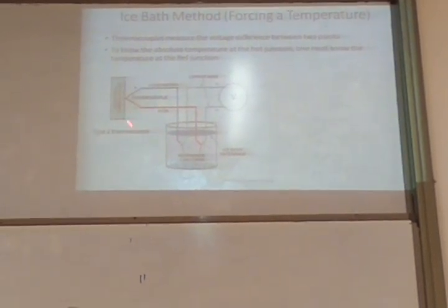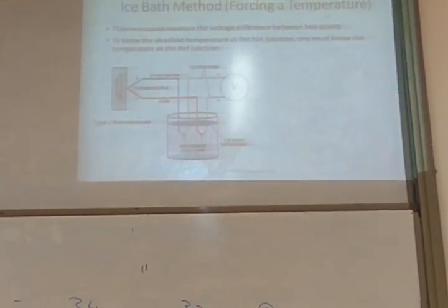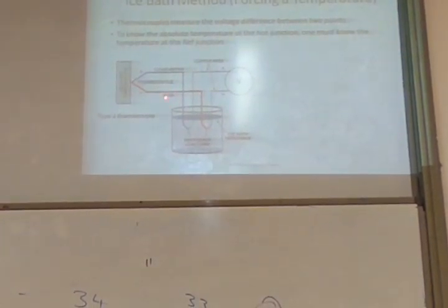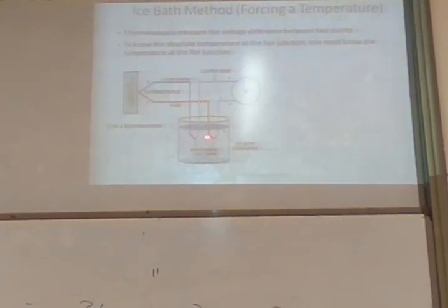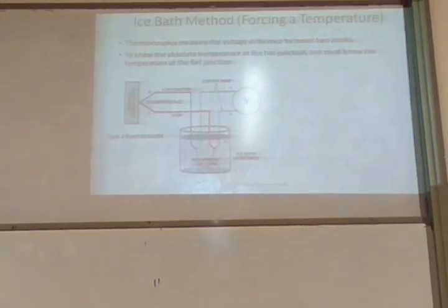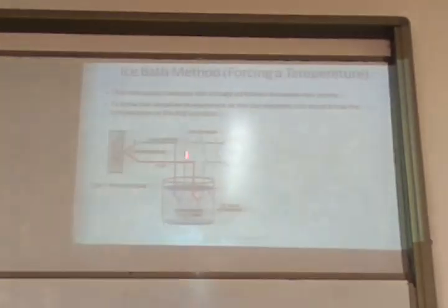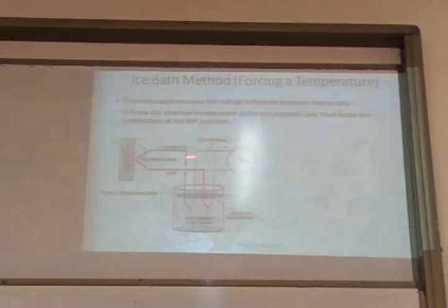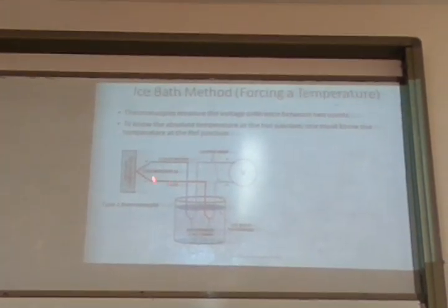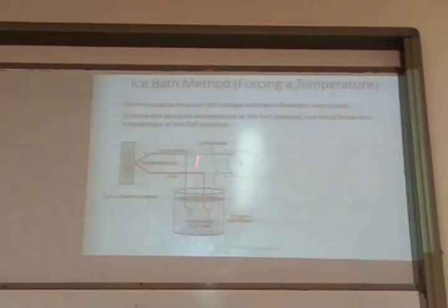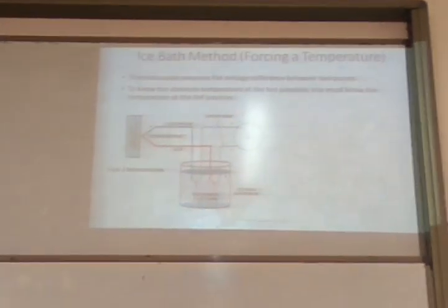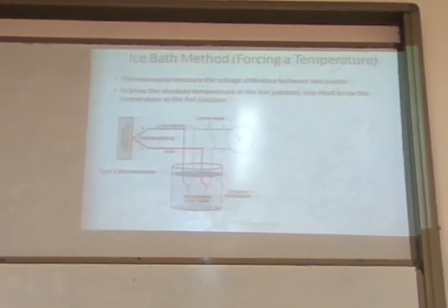This is the thermocouple part. Up to the thermocouple part, this should be the same wire. This is one material, let's say it is iron. The blue color line is another material, let us say it is constantan. That is a J-type thermocouple basically. I have mentioned it here. This is the J-type thermocouple that we have. And up to this point, it is two different wires. After this, this can be a copper wire, normally when we use it for measuring.